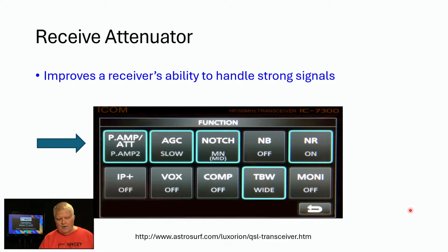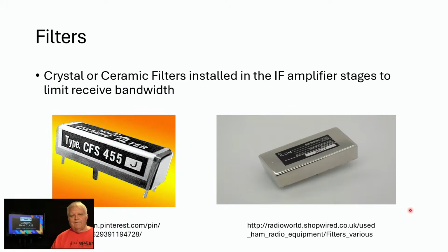With superheterodyne radios that have an IF, the filters that you install in the radio, whether they're crystal, ceramic, or otherwise, will set the bandwidth of reception. So you have a filter for CW and you have a filter for single sideband. Why do we use these filters, and why do we use the various bandwidths of these filters?